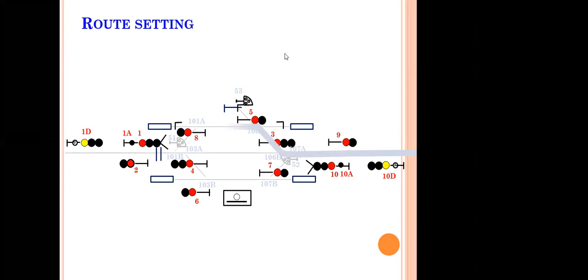So now I'm receiving a train on this loop line. The route is set for road 1 loop line. What are the points I want here? I want, as usual, point number 107 normal. Then only the train will travel from 107 to 106. I want 106 reverse. I want to divert the train now. I want a siding point, which has to be kept isolated, in the normal.